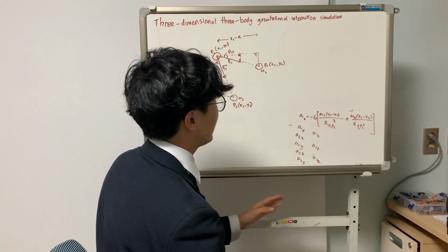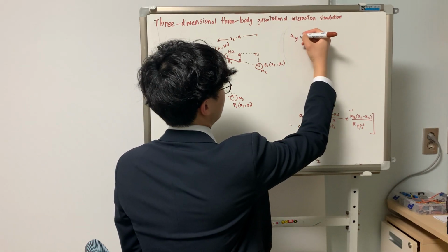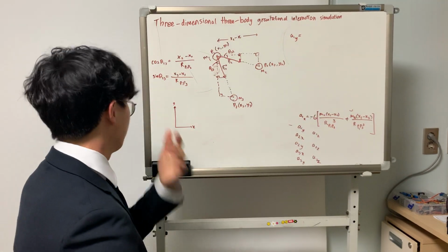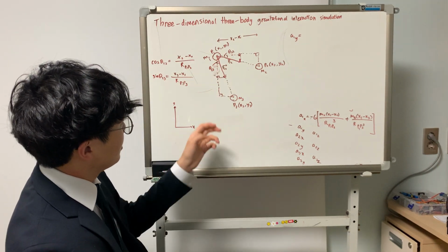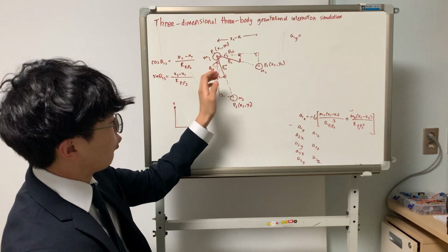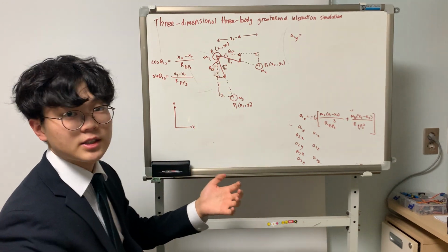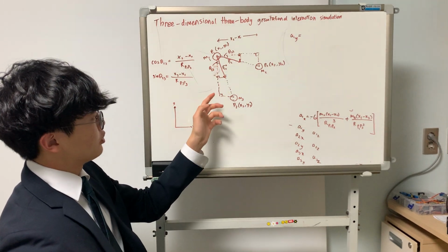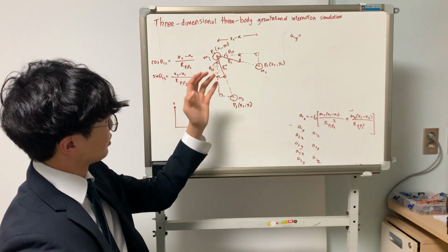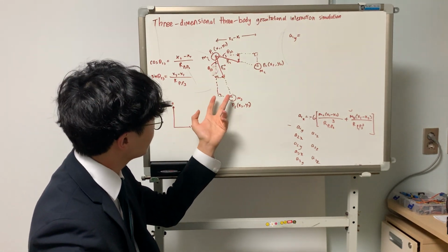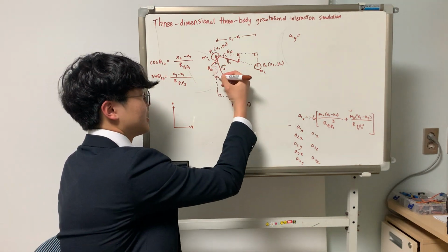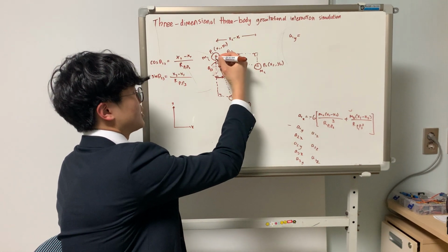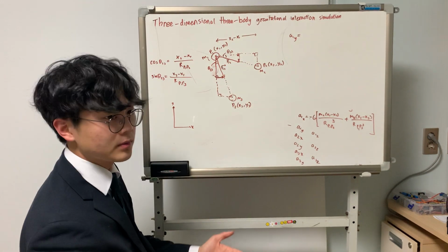Okay, let's look at a1y. What would a1y be? Well, we do the same thing. We have our forces, but now we don't multiply f13 times the sine. Now what we're going to do is multiply the force here times the cosine, because now what we're dealing with is not this force here, but this force that goes vertical.